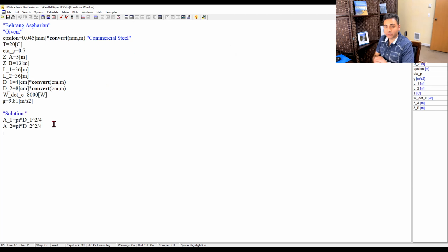There are a couple of other things I need to calculate or find: density and the viscosity of water at this particular temperature. So this is a technique I'm going to use. Rho, density, equals density of water, right? Water, I need two independent properties. T is the T that is given in the code, and I give it a quality of 0, which means liquid water, for ease.